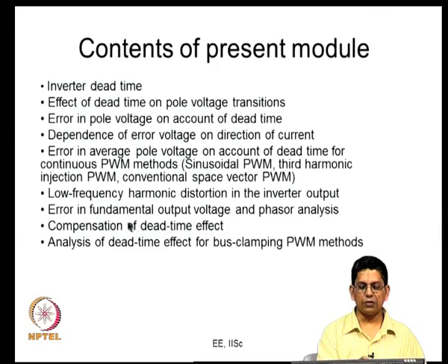The dead time affects the fundamental output voltage. It is not what it is supposed to be. There is a certain amount of change. The fundamental voltage amplitude may be changed. The fundamental output voltage, the ideal value and the actual value, could be different. They could be different in terms of their amplitudes or in terms of phase or both. So that is something that we would look at.